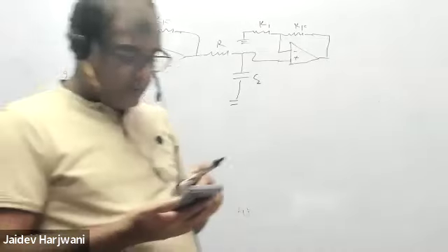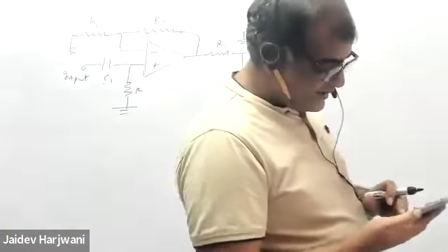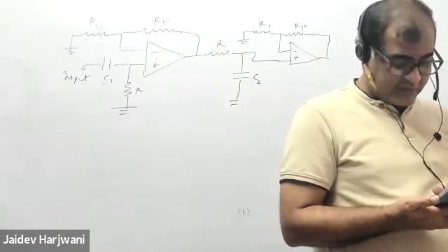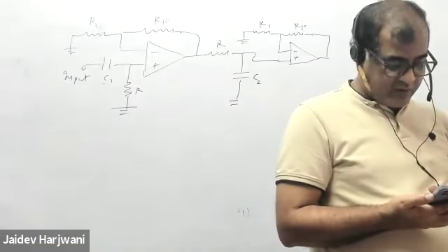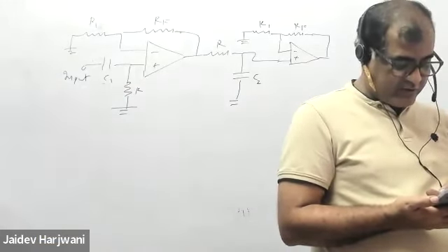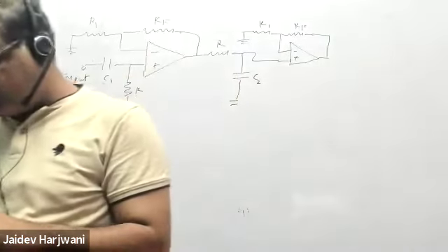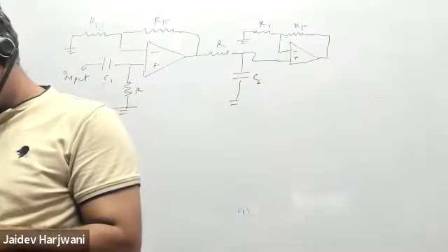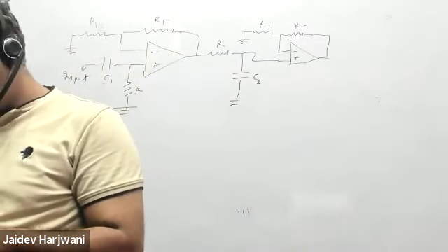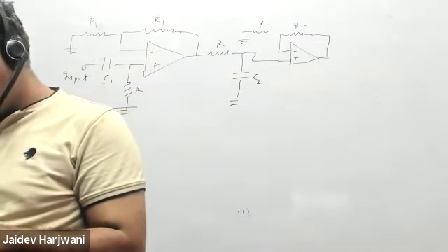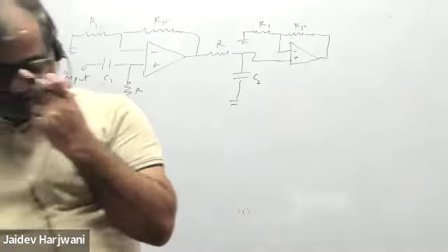This question number is 21. This is the circuit diagram of a band pass filter, with high pass and low pass sections, shown below, R equal to 10 kilo ohm. In order to get a lower cutoff frequency of 150 hertz and an upper cutoff frequency of 10 kilohertz, the appropriate values of C1, C2 you have to find, respectively.